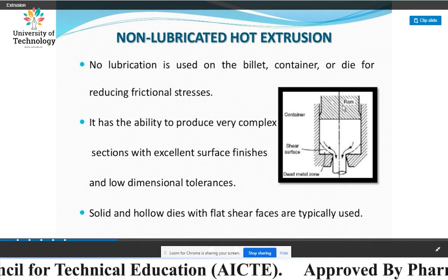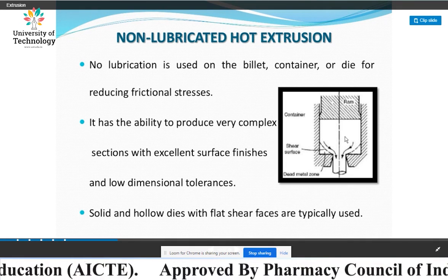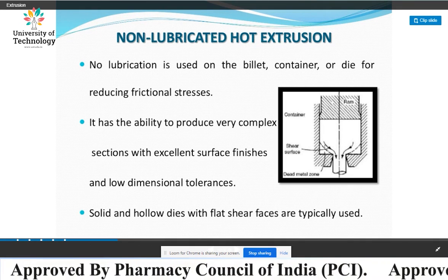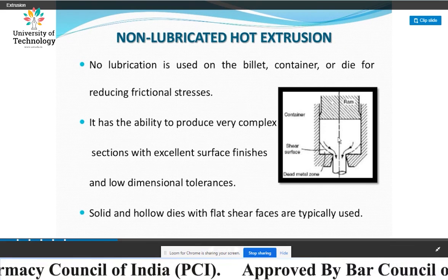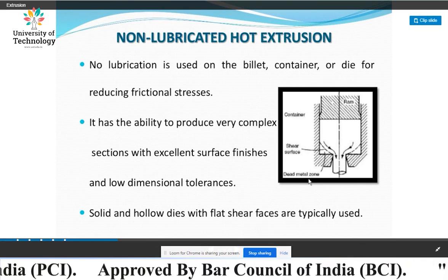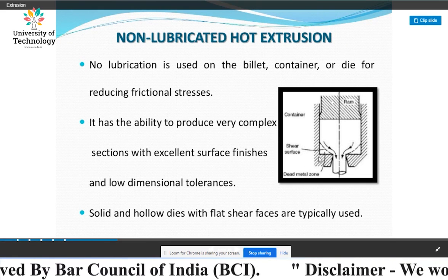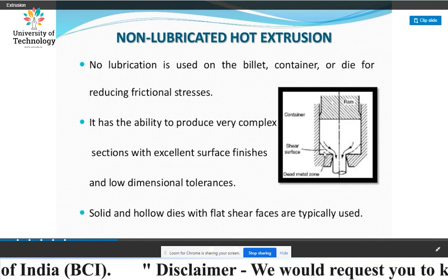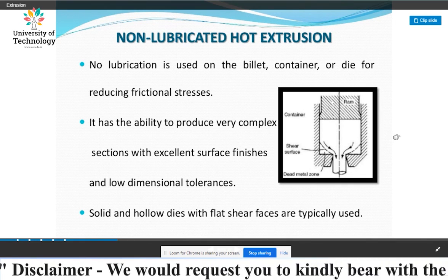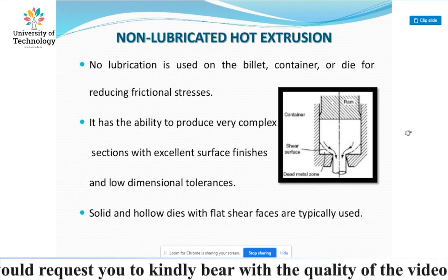And we can see in the figure that here is the ram, and here is the billet, and the shear surface is inside the container, and the dead metal zone. Here, a corner has a dead metal zone. That's a basic drawing of the non-lubricated hot extrusion.